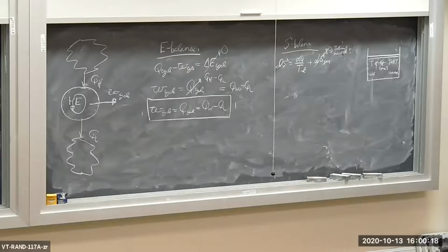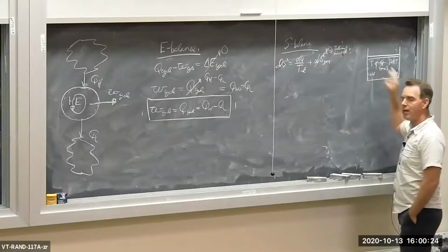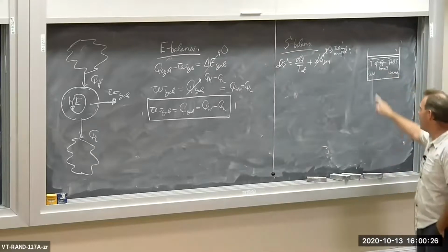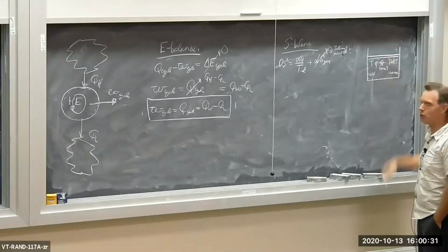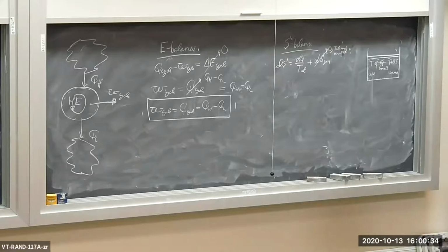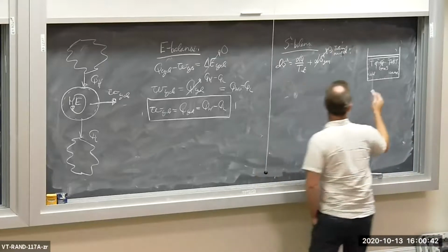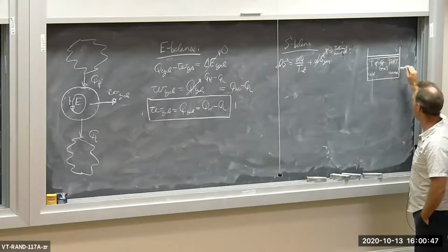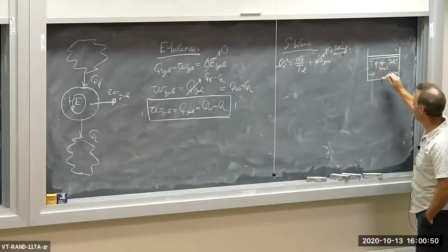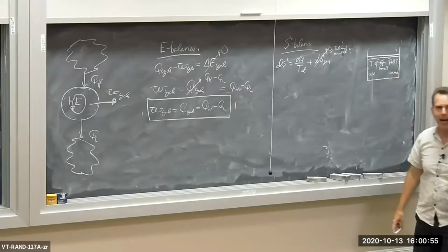So what that means is the temperature inside of my gas cannot vary spatially. There can't be a cold part and a warm part. It all has to be the same temperature inside, or I get heat transfer across a finite temperature difference inside my system. That means that the interaction temperature, or the temperature that I measure anywhere on the surface of my system, where the heat crosses the system boundary, has to be equal to the gas temperature.